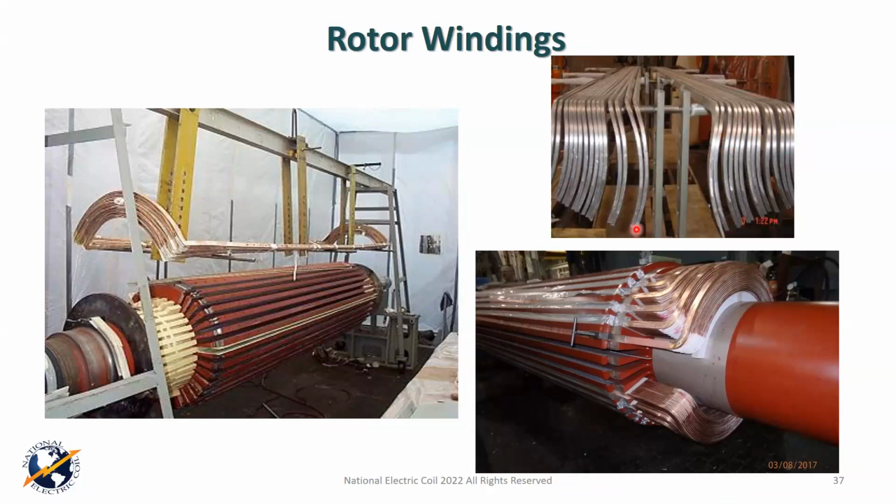And then you have a braze joint in the middle of the saddle. Going back again to the Alstom design, this is a common one on a lot of the Alstom machines. In fact, on the larger ones, on those WX and WYs, that braze joint in the middle is problematic because of some of the air channels they have in the conductor. To do that justice, I need quite a bit more time than we're going to have today. But if you're curious about that, give me a call and I can share some information with you.